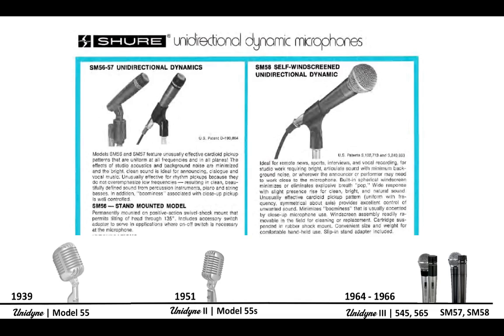There were some minor differences, like the introduction of neodymium magnets in dynamic microphones, and refinements going from cardioid to supercardioid and hypercardioid polar patterns, basically updates to the same principle. Yeah, the theory is basically variations on a theme, and we can put a different magnet or tweak the coil or tweak the diaphragm, but they were all based upon the theory of the Unidyne III.